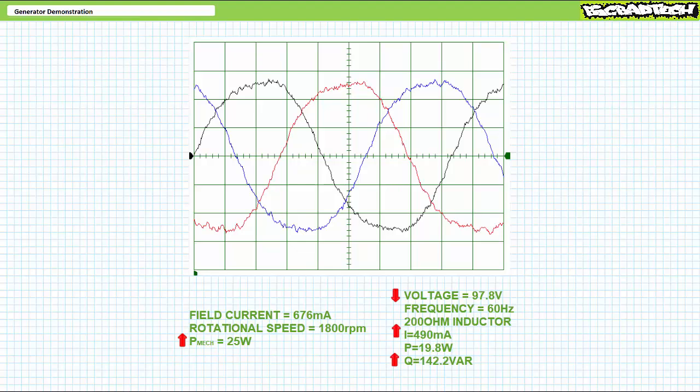Given this prime mover is operating in constant speed mode, speed remains at 1800 RPM and frequency remains at 60 Hz. Our concern is a small reduction in voltage for this increasingly loaded inductive condition. This is again to be expected, but not good, given an electrical distribution system should ideally maintain stable voltage magnitude. A quick solution to this disturbance is to increase field current.